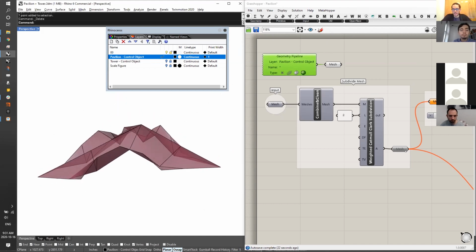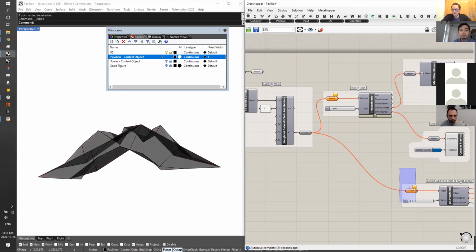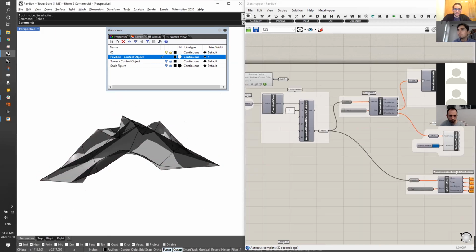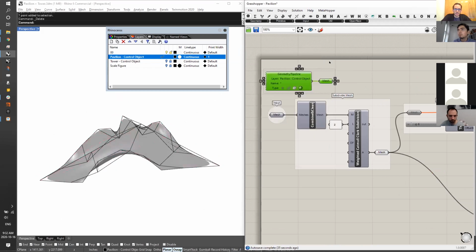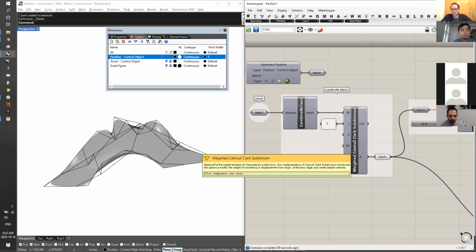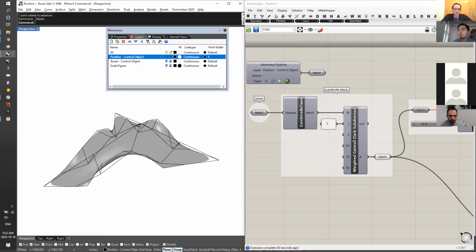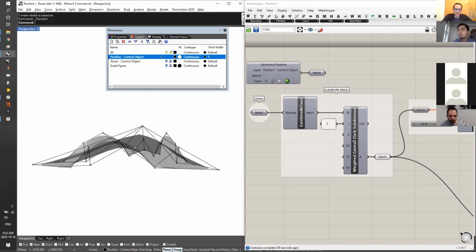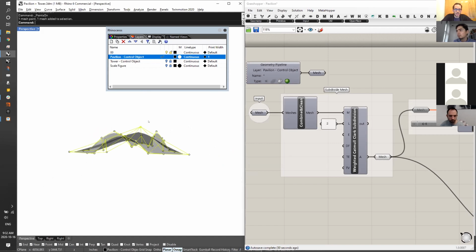So in this case, I'm going to go ahead and turn this off and turn this off to describe something. Okay, so we're going to have this turned on. And as you can see, with a very simple Catmull-Clark subdivision from the Mesh Plus plugin, at a level 2, we can start to get an object that's pretty much sculpted, for lack of a better sense, but it's also really easy to edit and work with.